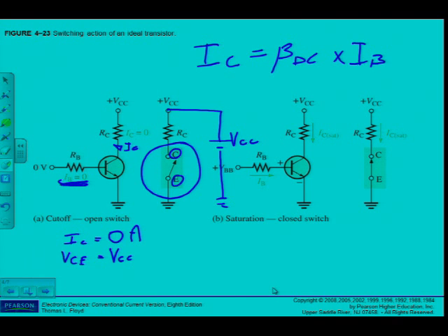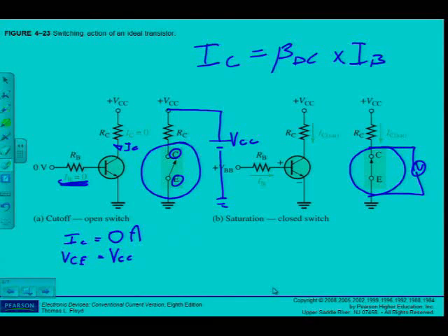On the other hand, at the closed switch, the transistor is in saturation. I can see here that the switch is now closed. If I measure over there with a voltmeter, I should ideally measure 0 volts, but we've seen it's not an ideal device. We've also mentioned that for a transistor, especially as used in this book, we assume it to be approximately 0.2 volts. And the current that flows through this device will now be the maximum current, which we've seen is called IC sat.